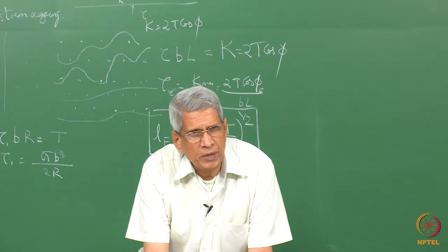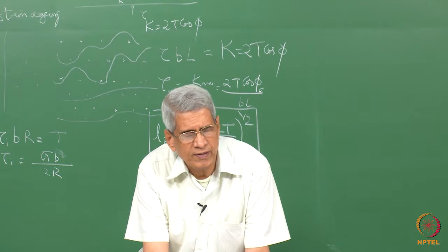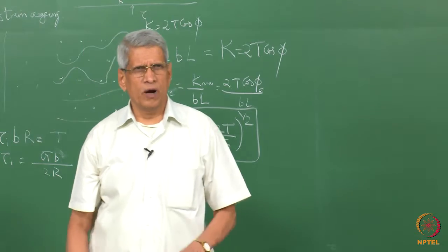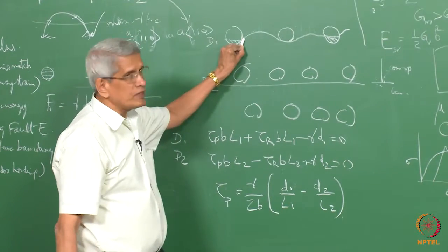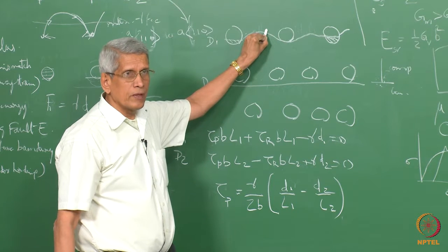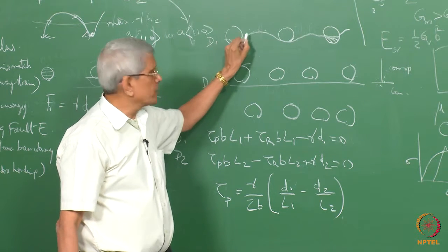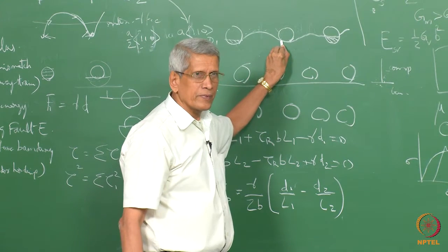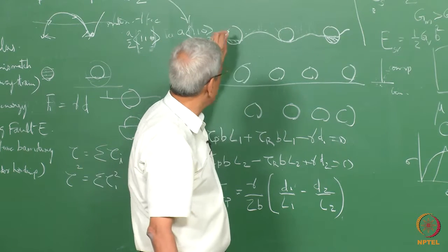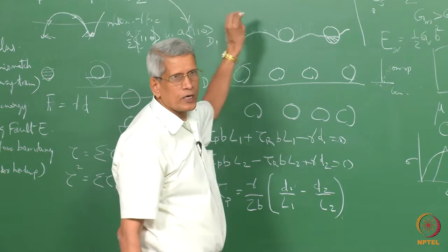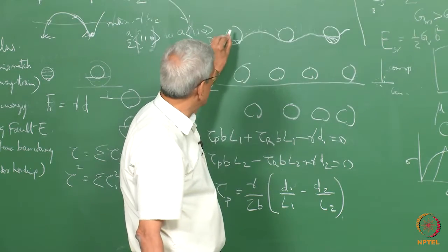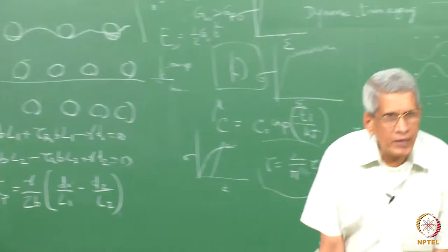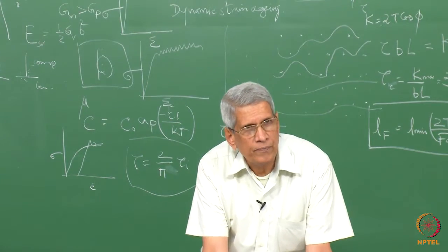This gives the expression to find out the critical stress which is necessary. This will be the increase in yield strength which will occur when we deform a material. In all these cases you can see that the dislocation has already been bent. Suppose even before the dislocation has entered, it has already reached a semicircular shape. Then it will not be able to enter into the particle. Instead, looping will take place. That will occur when the particle spacing is large, for the same size of the particle.